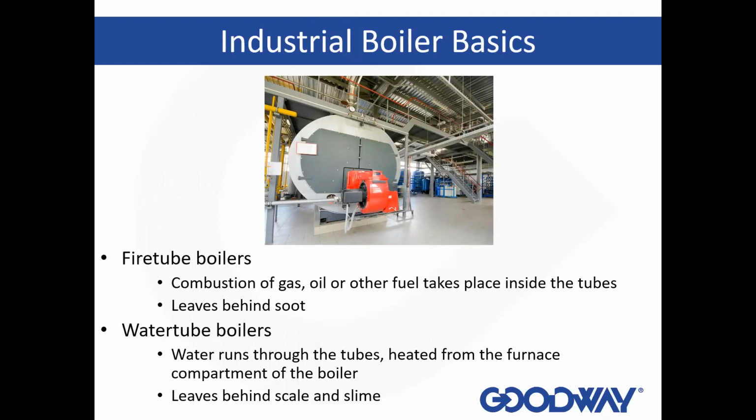Again, the type of boilers that we're talking about, we'll break down into two categories. Firetube boilers, which Cleaver Brooks is one of the bigger ones, and it's depicted in some of the pictures here. Basically, it's fuel running through the tubes in the boiler. That's where the burning is taking place, and the fuel oil that's being burned leaves behind a deposit. Sometimes it's fuel oil, sometimes it's bunker oil. Some places like greenhouses might burn wood, and each type of fuel leaves behind a different type of deposit. Those deposits will insulate the tube and hurt the efficiency of your boiler. And that's talking about fire tubes.